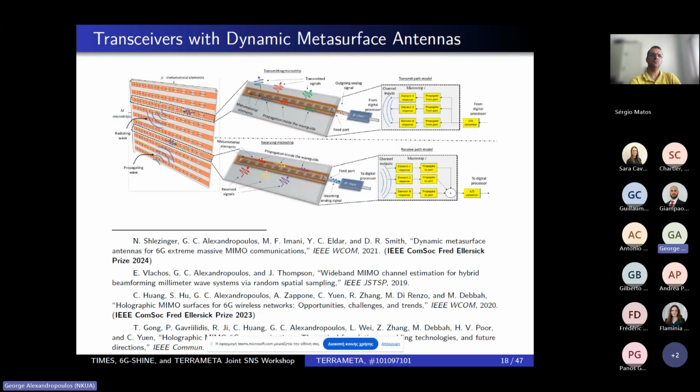But in the metasurface, you have the elements grouped in subgroups of elements placed on specific waveguides, and these waveguides being connected with either a transmitter or a receiver chain, realizing a transmitter or a receiver respectively. There have been various works trying to explain which are the gains in terms of power and cost efficiency compared to conventional XL MIMO architectures based on phase shifts.